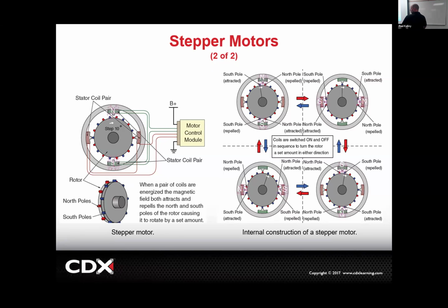So if you want to know if it's the motor, you go in with the scan tool and you say, show me empty fuel, show me 50%, show me 100, 90, 80, 70, 60, 50, 40, 30, 20, 10, 0. You can actually sweep it with the scan tool. If the motor's no good, the sweep won't work. Make sense? But if the sweep works and the needle goes to all the correct spots, but then you start the car and it's reading wrong, that would give you an indication that maybe it's on the sensor side, right?